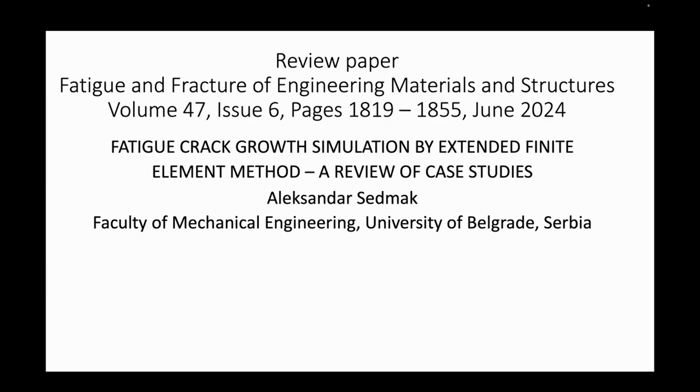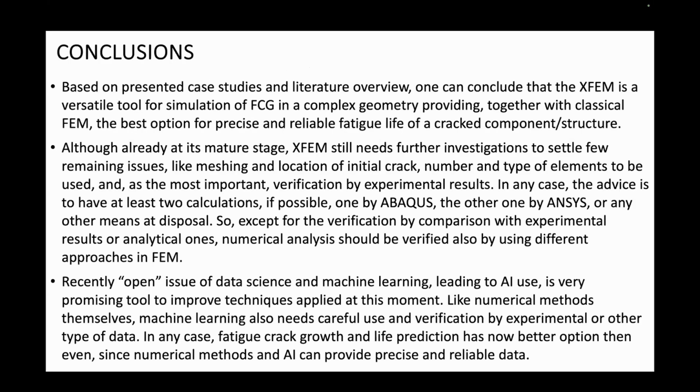So, conclusions are based on these case studies, the literature overview, and some other case studies that we didn't have time to present. But the major conclusion is that the extended finite element method is a versatile tool for simulation of fatigue crack growth in complex geometry. That's quite important, because for simple geometries you actually don't need the finite element method.